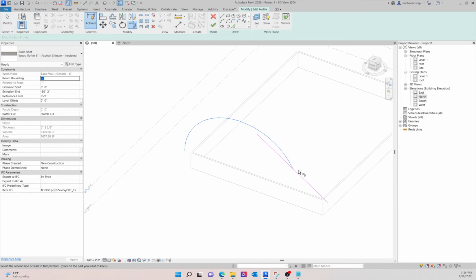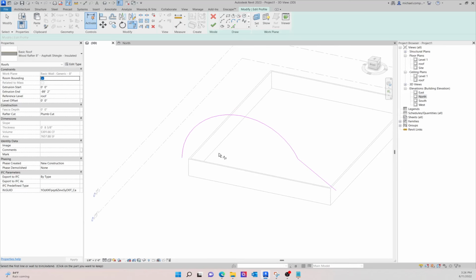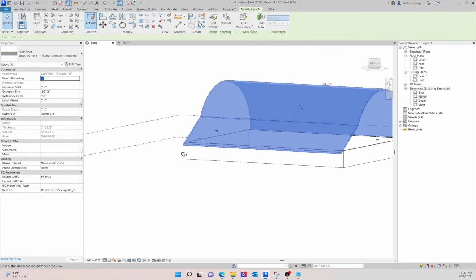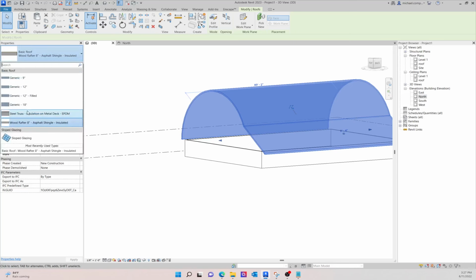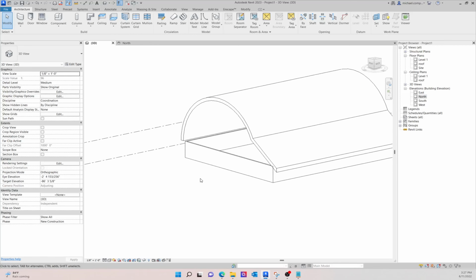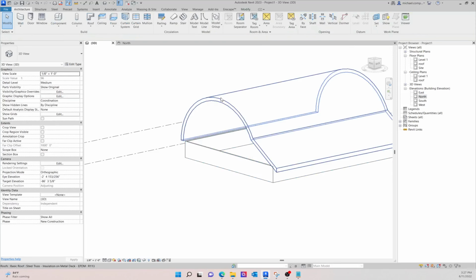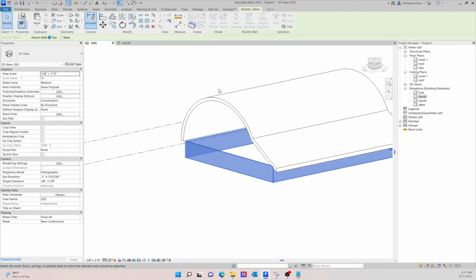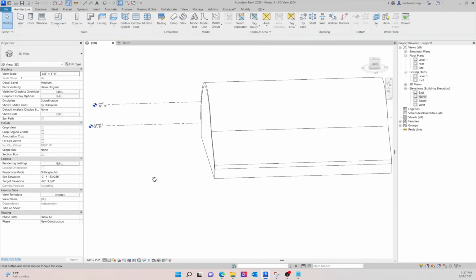Okay. All right, so the point I'm trying to make is whatever shape or profile you can think of, including a really weird sort of wavy shape, you can model. So I hit OK, there's my thing, right? And again, it's based on this wood rafter. If I really wanted it to be steel truss, it could be steel truss, it just changes the thickness or the composition of that. Now, same is true here. Select all the walls, hit attach top base, it fills in the gaps. And what you have left over is the roof.